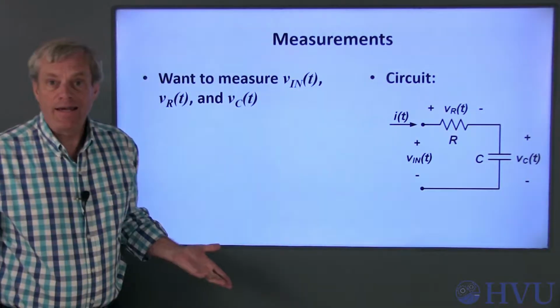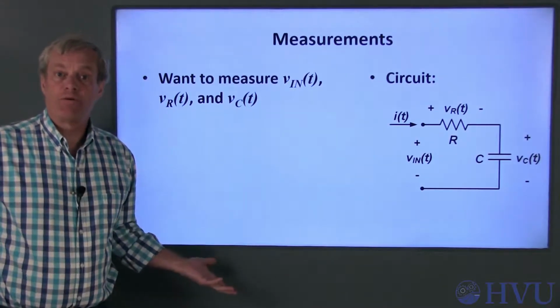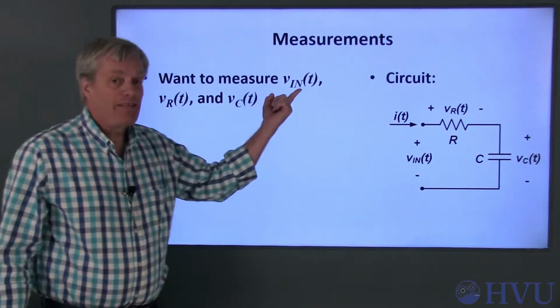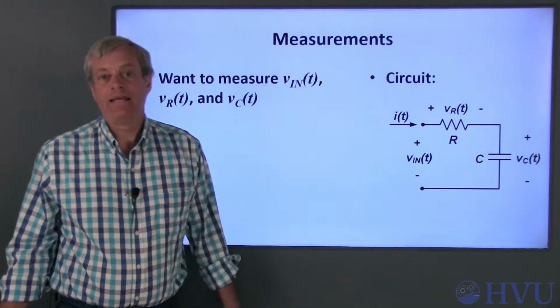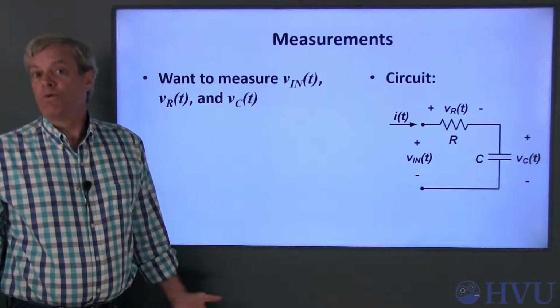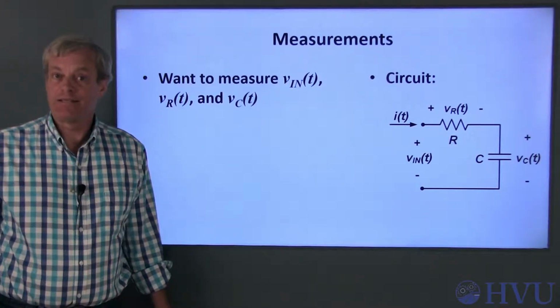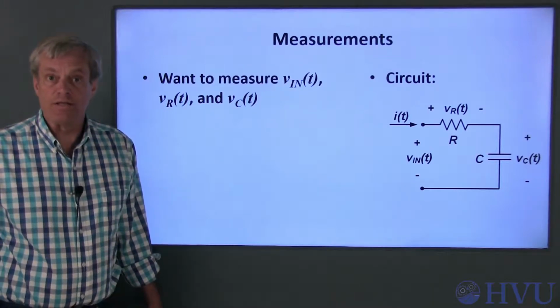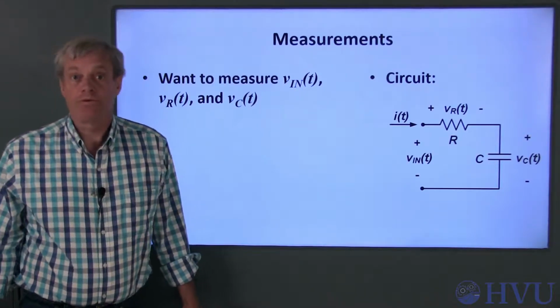To get both magnitude responses, we need to measure three parameters: the capacitor voltage, the resistor voltage, and the input voltage. Sadly, our USB-based oscilloscope has only two channels, so we either have to run separate tests to get the two magnitude responses or come up with a trick to get all three values at once. I'm going to use the tricky approach.